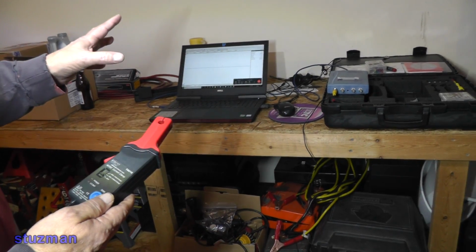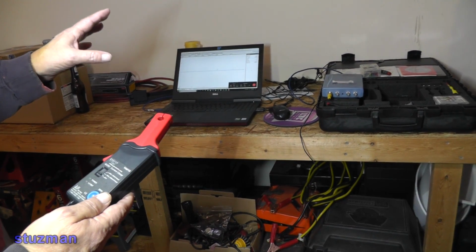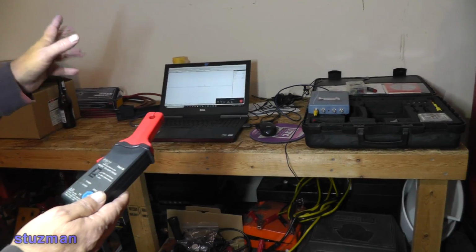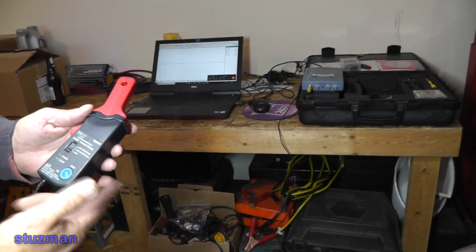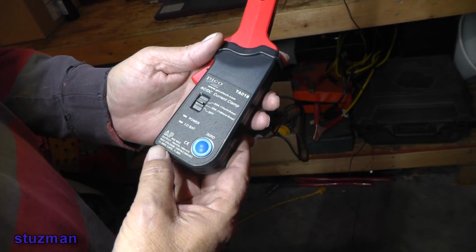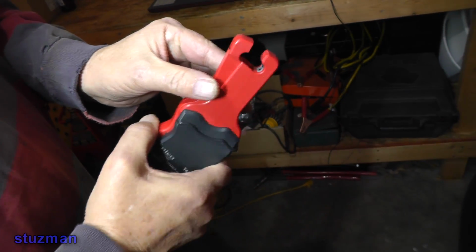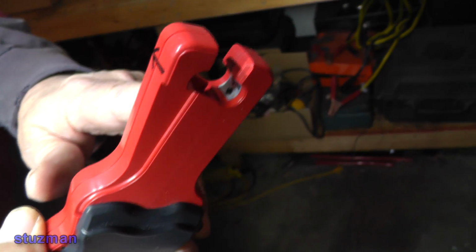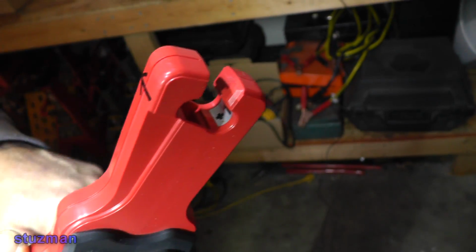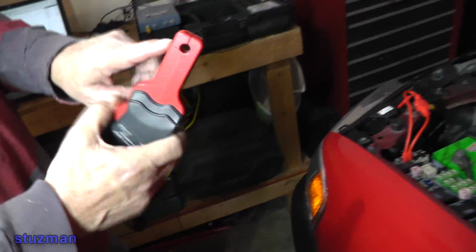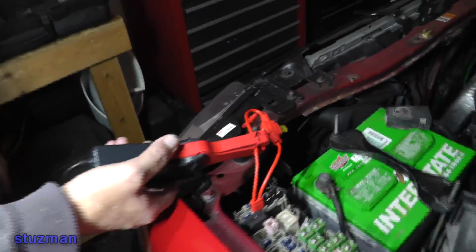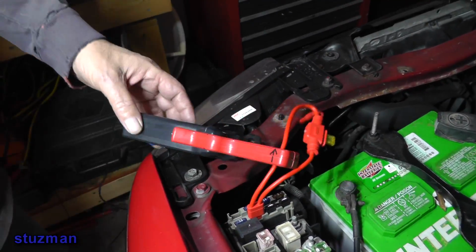Alright, so I've got the PicoScope hooked up here, and I'm going to be taking the waveform of the fuel pump just for my database. So I'm going to be using a 20 amp clamp. I'm going to set it for the 20 amp mode. Now if you look inside the jaw, you see that plus sign and that arrow just like we did before. Again, conventional current flow. So I have my arrows on the outside of my clamp so I can right off the bat tell that it's going to be going this way, just like what we did before.